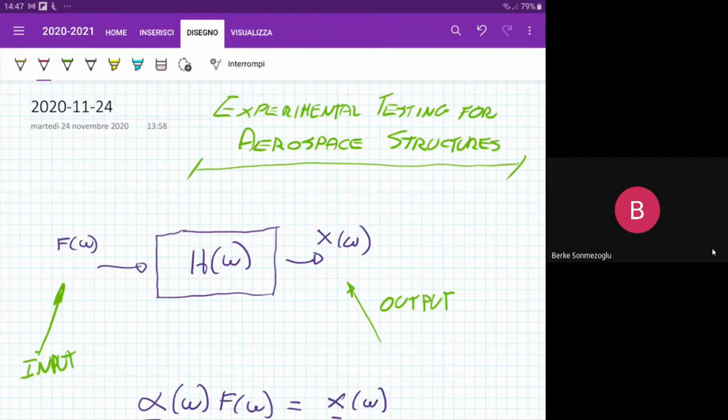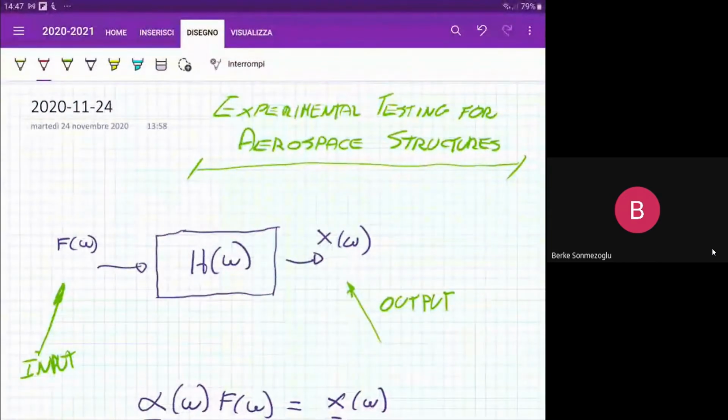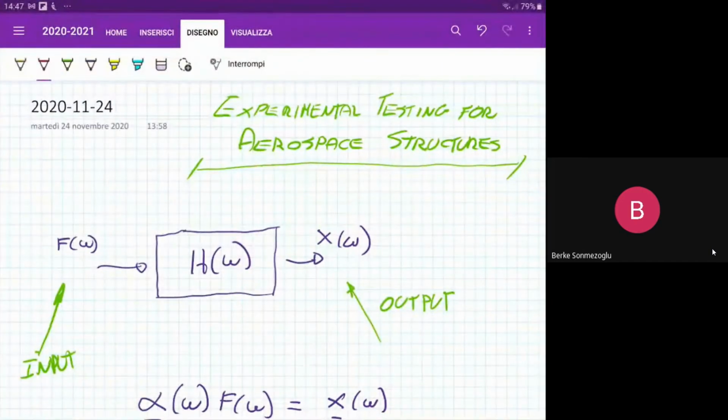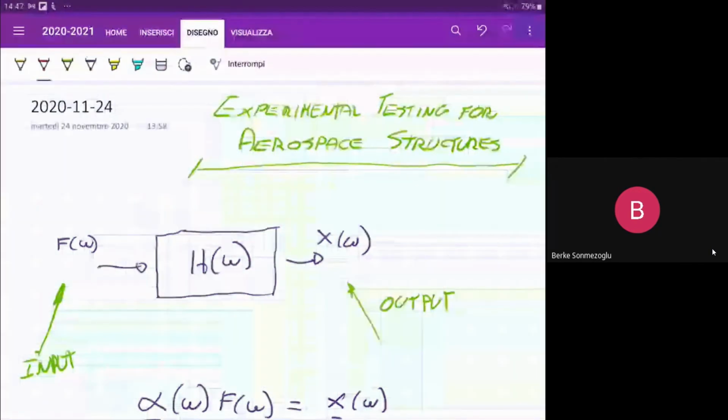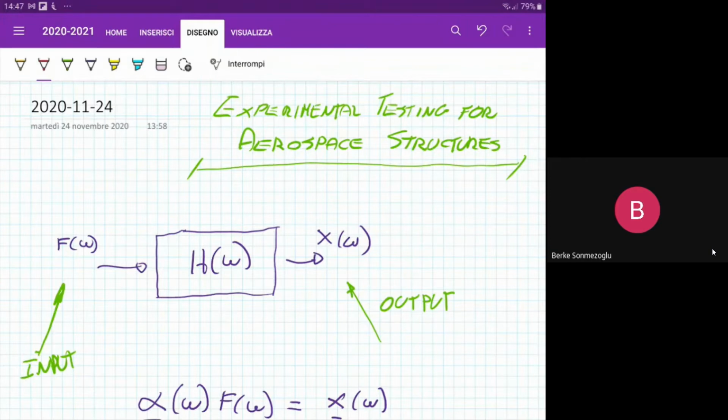As we already discussed, when dealing with a numerical model, your spatial model, that is the mass, stiffness, and even damping distribution, could be represented, for example, as mass, stiffness, and damping matrices in a finite element model. And using that, you can easily solve the eigenvalue problem associated with this spatial model.